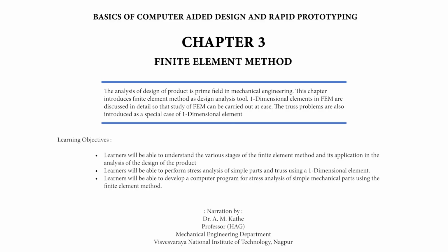Q1, Q2 represent the components of the displacement that is taking place at node 1. Similarly, Q3, Q4 represent the components of the displacement that is taking place at node 2. Thus, Q equals Q1, Q2, Q3, Q4. Q represents the displacement matrix when the components of the displacement at nodes 1 and 2 are considered. Q dash is important because the procedure of the one-dimensional element can be applied to solve the truss problem. The relation between Q dash and Q can be established as follows.